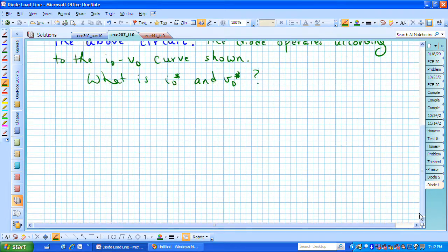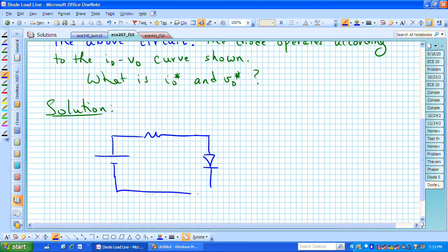Or in other words, in terms of a solution, we could think of this looking like what you're more comfortable analyzing, a circuit with this structure. Here's terminal A and here's terminal B relative to the diode. Here is now a 1200 ohm resistor, and this is now a 12-volt Thevenin equivalent voltage, which is the DC voltage that we had anyway.